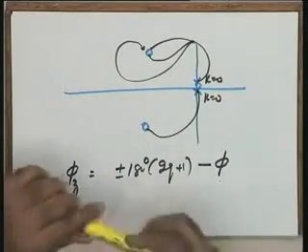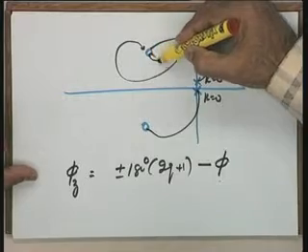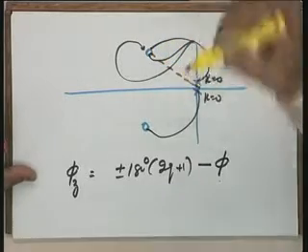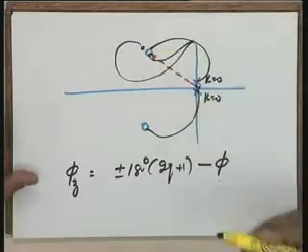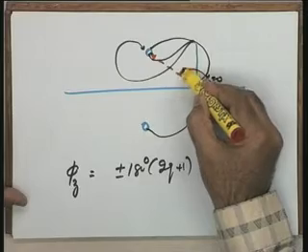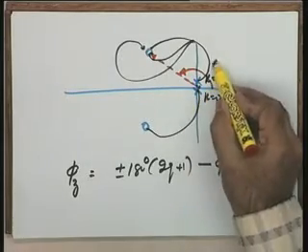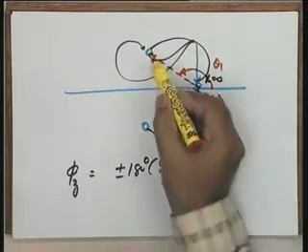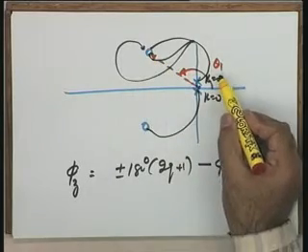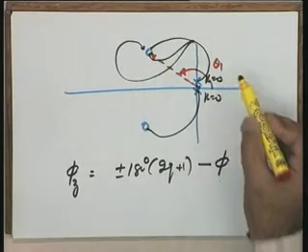In this particular numerical, for example, you just take this zero. So the net angle contribution is double of this because there are two poles. Suppose this is theta 1. So the net angle contribution at this zero is minus 2 theta 1.